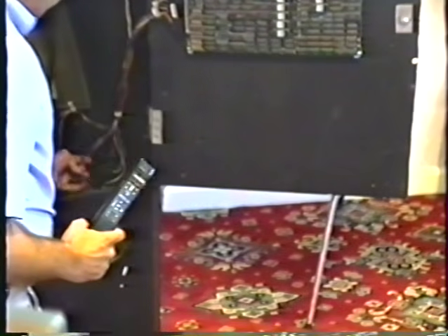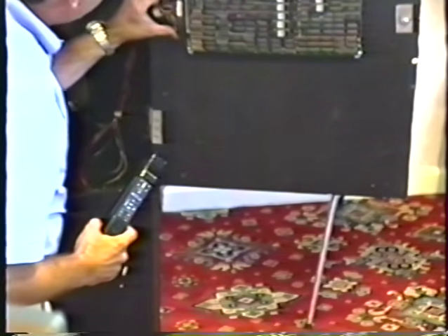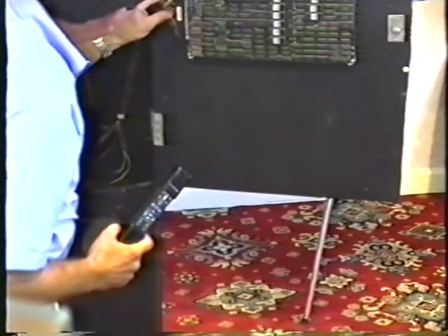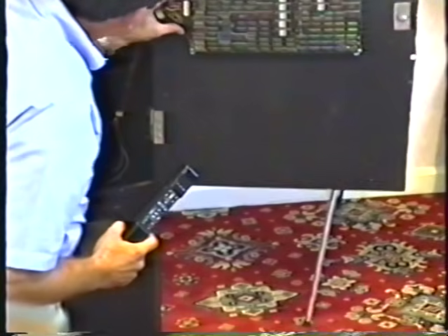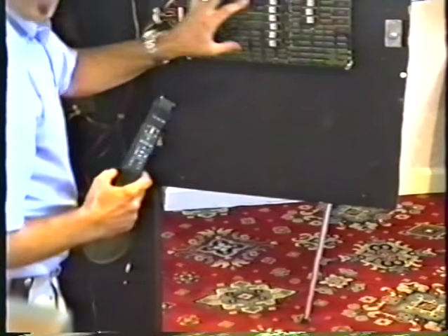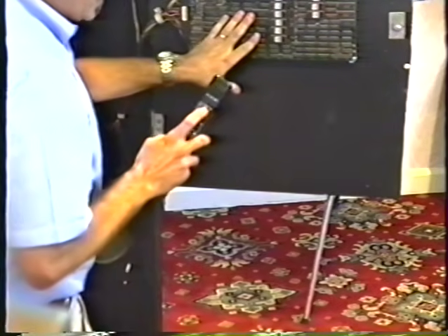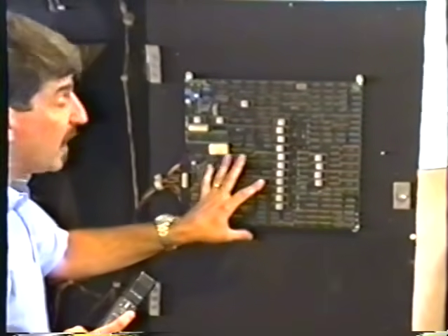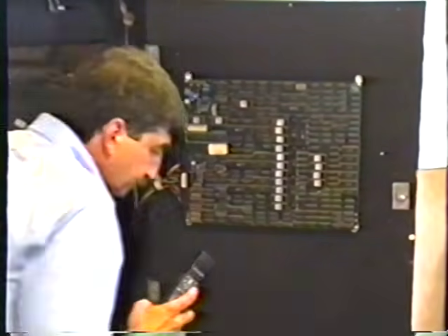So by the time the current gets out of this power supply, through these wires, through this connector, which is not even very tight actually. Wow, it's pretty darn loose in fact. Through this connector and onto the logic board, it's real easy to lose a few tenths of a volt. So it's real important that we measure the voltage on the logic board.